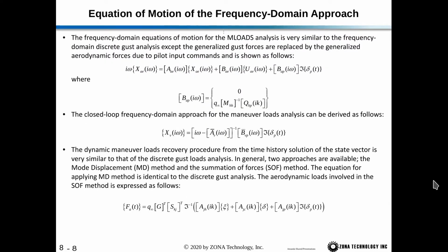Now we'll look at the frequency domain approach in ZAERO. So the frequency domain equations of motion for the MLOADS analysis is very similar to the frequency domain discrete gust analysis, except the generalized gust forces are replaced by the generalized aerodynamic forces due to the pilot input commands, as shown by this equation. So the first two terms here on the right-hand side are the same as we've seen before, but now our new external forcing function is our delta P, so that is the pilot input.